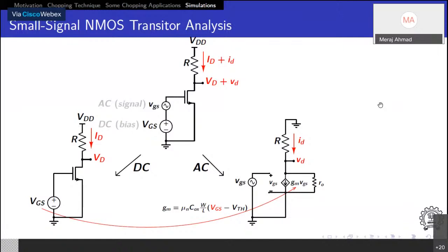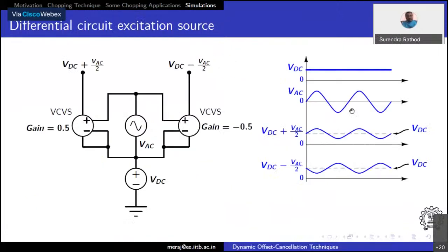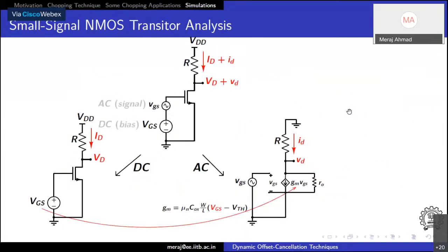So what we will do is, for simulating a differential circuit in Cadence, we need to have a single voltage source. Okay, there is a question: what is periodic steady state, PSS, analysis? PSS is periodic steady state analysis. It is a DC analysis which is done at different instants of time.